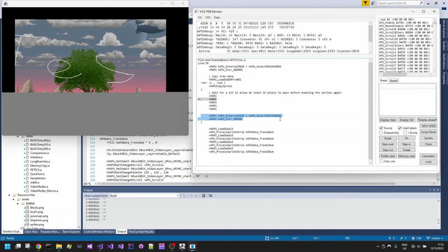Now, what we can do is that we can optimize this, because we want to have some other palette changing and we want to have some extra X scrolls and everything like that done. So what we can do is that we can update chunks of 4 sprites on each scan line and keep on going down the screen like that. That's basically what multiplexing is: reusing the sprite definitions as we go down the screen.